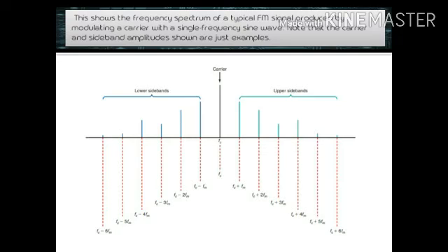Despite this, the bandwidth of an FM signal is usually much wider than that of an AM signal with the same modulating signal. In addition to this, as the amplitude of the modulating signal varies, the frequency deviation changes. The number of sidebands produced and their amplitude and spacing depend on the frequency deviation and modulating frequency. Keep in mind that an FM signal has a constant amplitude, since an FM signal is a summation of the sideband frequencies. The sideband amplitude must vary with the frequency deviation and modulating frequency if their sum is to produce a constant amplitude but variable frequency FM signal.